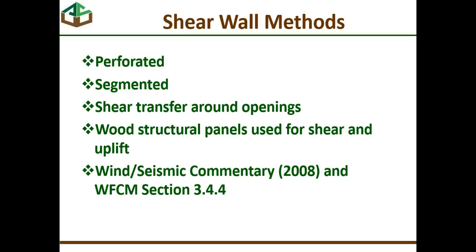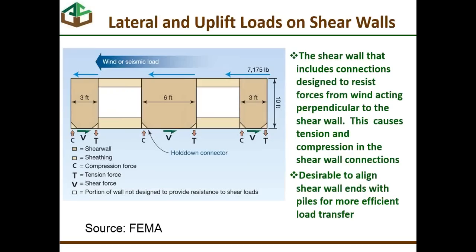A lot of this information is covered in the Wood Frame Construction Manual's commentary for wind and seismic design, and you see the section reference there. You can also use wood structural panels for both shear and uplift, and there are tables in the manual and discussion about how to do that. So let's look at both methods here real quickly.